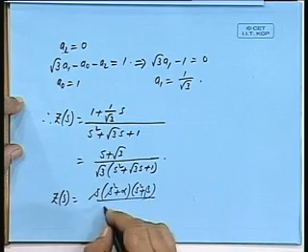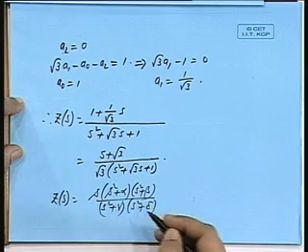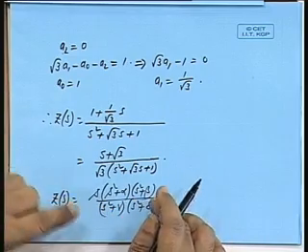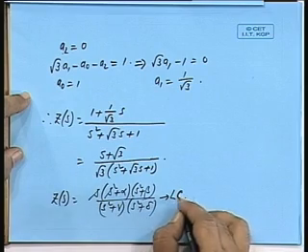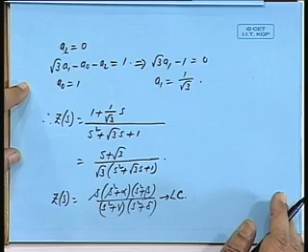For example, Z(s), if you are having functions like s squared plus alpha, s squared plus beta, s squared plus gamma, s squared plus delta, functions of this type, and if the poles and zeros are interlaced, coming alternately, then it is an LC function, is it not? You can have Foster 1, Foster 2, Cauer 1, Cauer 2 realizations, and in those realizations you have the minimum number of elements, they are canonic forms.